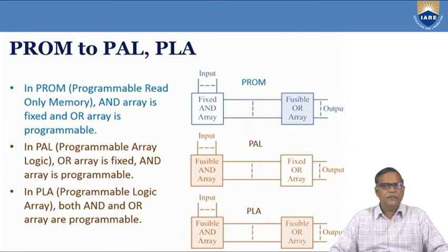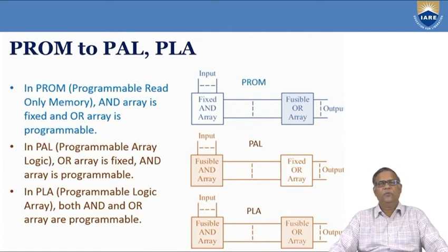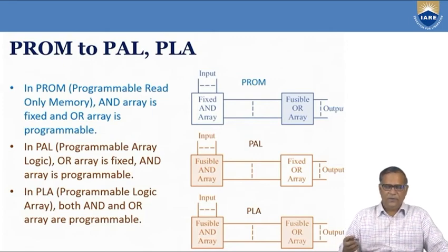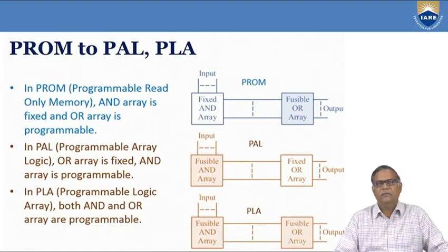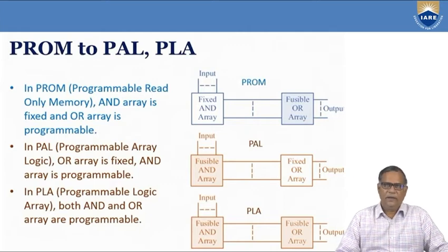The PLDs have three types: PROMs, PALs and PLA. PLA means Programmable Logic Array, PAL means Programmable Array Logic, PROM means Programmable Read-Only Memory. These devices contain an array of AND gates and OR gates, and we are going to follow certain conventions.